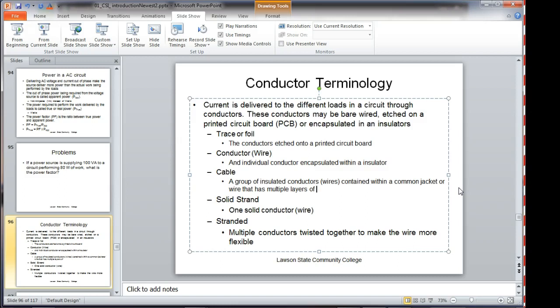If I've got 50,000 volts and insulation rated at 75,000 volts all the way around, and you move that potential over to one side, then the insulation will break down. So they put layers inside that high voltage cable to keep the potential in the center of the cable.